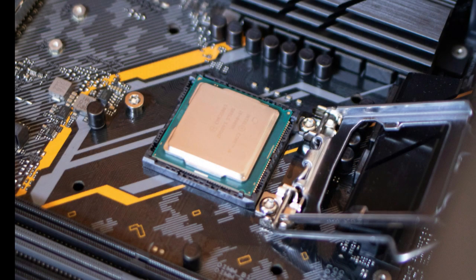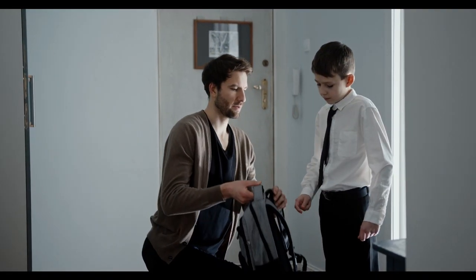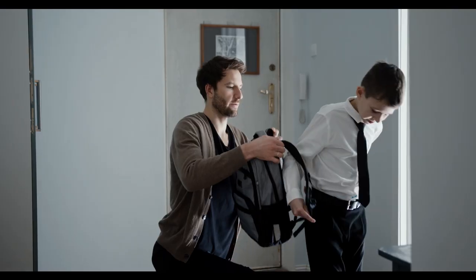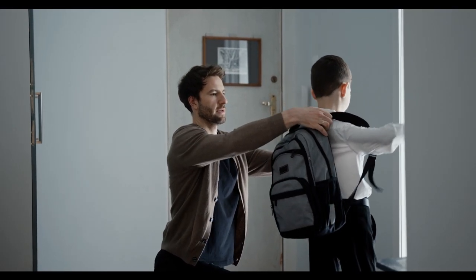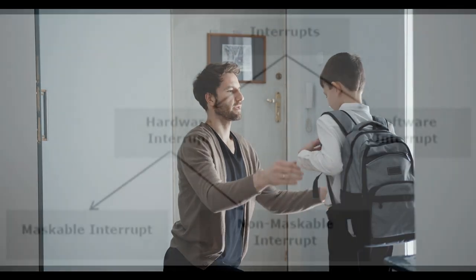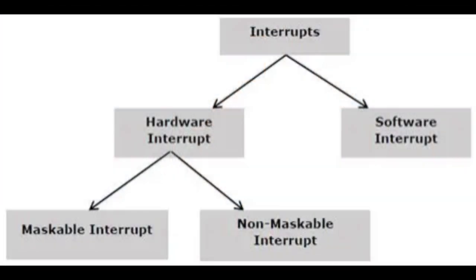Why are interrupts needed? Without interrupts, the CPU must constantly check devices using polling, which wastes CPU time, slows down response, and reduces efficiency. With interrupts, the CPU responds immediately. No need for continuous checking. Better performance and faster systems. Interrupts are mainly of two types. One is hardware interrupts, generated by external devices. Two is software interrupts, generated by program instructions.